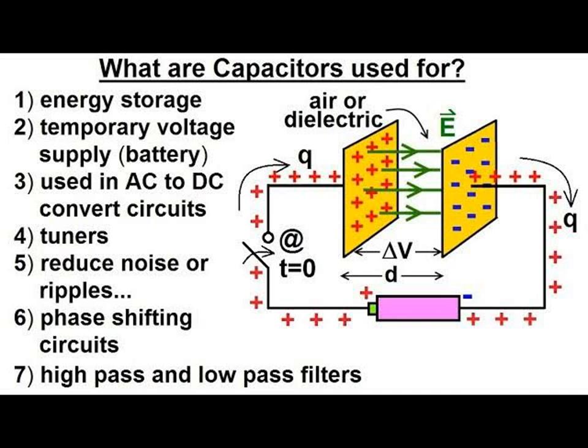And it is pretty simple in its dimensions. Next, so when we talk about current in parallel, you talk about algebraic sum. Quantity of charge in a parallel, algebraic sum. Energy stored in parallel, algebraic sum. But as for series, they are the same. Good. Now that takes us to the amount of electrical energy stored in a capacitor.